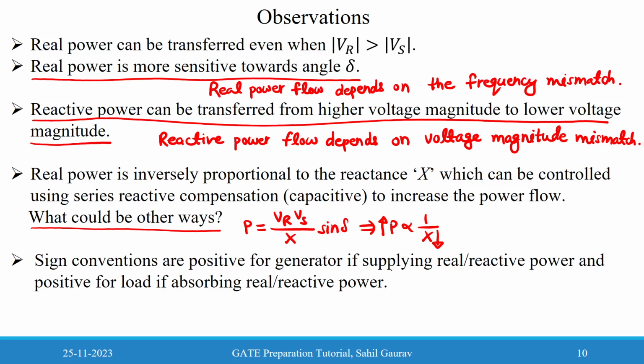Yes, sir. The most other possibility is that you can decrease the reactance using the double circuit line. If you are having parallel circuit lines, a double circuit line for decreasing the reactance will reduce your reactance by half. And bundle conductors we use for decreasing the reactance.